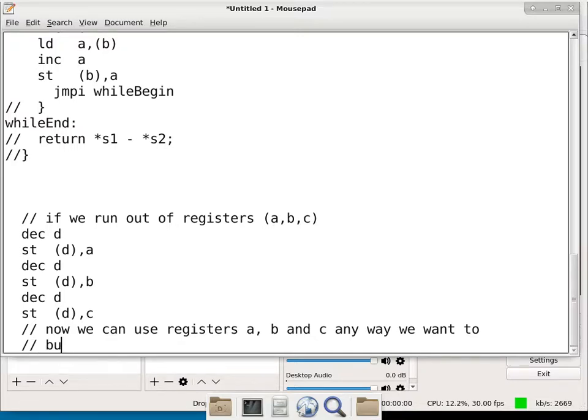But keep in mind that 3 more bytes are pushed on the stack, which also means if you need to go back to one of the parameters, they're no longer the distance that we knew before, because the distance that we knew before is based on the assumption that the stack pointer points to the return address. Now it is pointing to 3 bytes below what we expect it to be, which also means the calculation is going to be off.